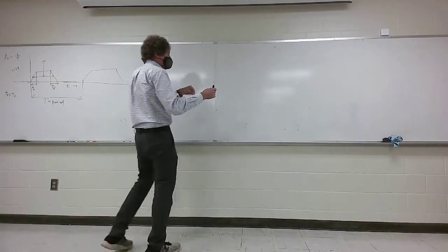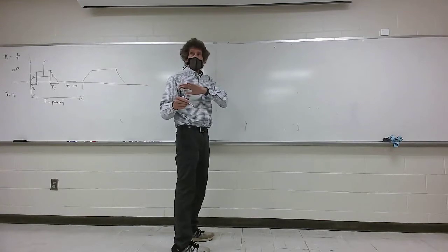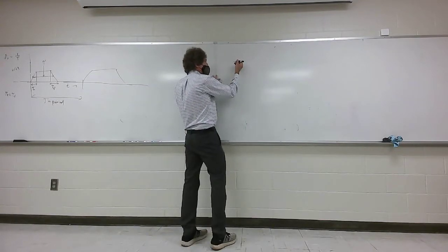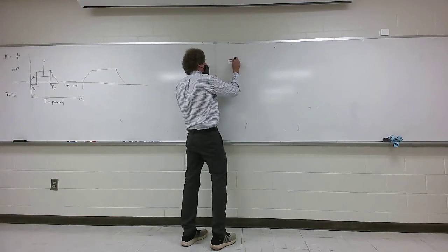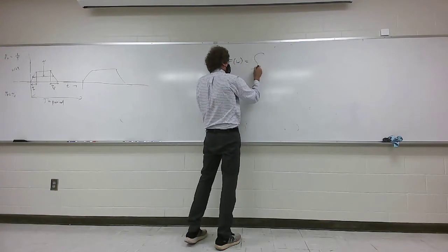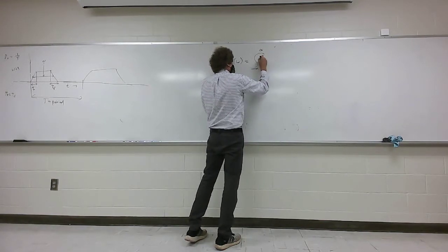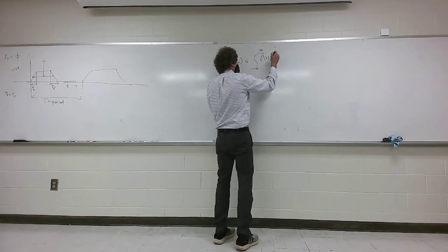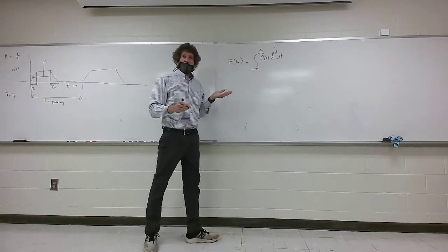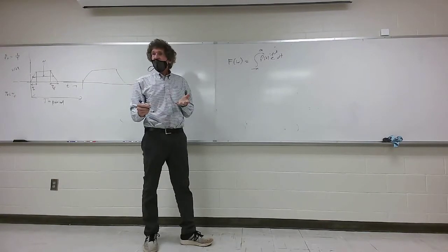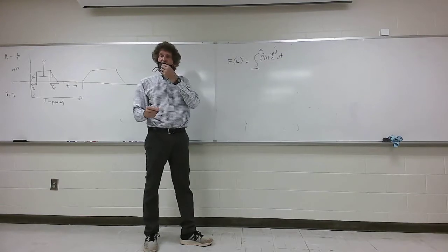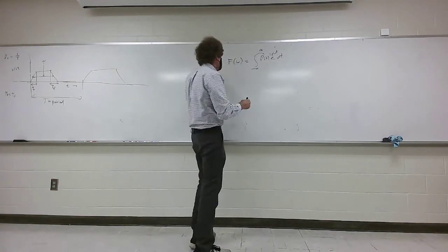So if we go into the frequency domain, what I like to do is first go back to some basic frequency domain transforms. When we talk about the Fourier transform of a signal, that's generally the integral from minus infinity to infinity of f of t e to the minus j omega t dt. Y'all remember that? That's fundamental, right? And we would use this if it's an energy signal, correct? If it's a repetitive signal, then we use the Fourier series.